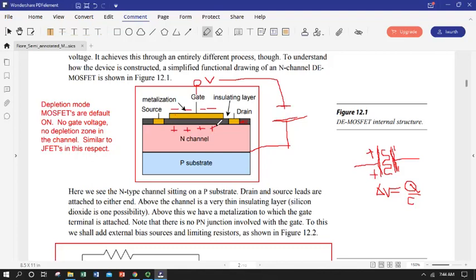Okay, well, if I have a positive charge in an N-doped semiconducting material, what that means is I've annihilated a bunch of electron charge carriers, and I've created a depletion zone. You can think of it as I've driven the charge carriers away. So I've driven the electrons away from this area adjacent to my oxide layer. So now current has to flow through a more restricted channel.